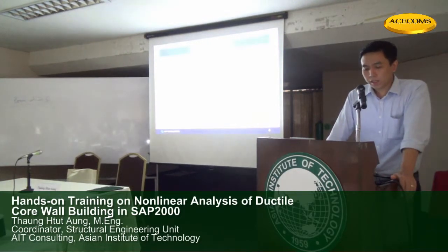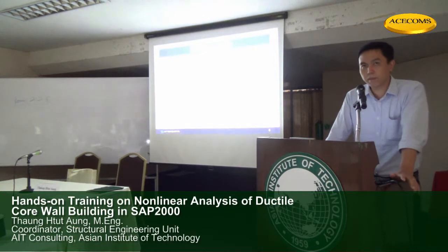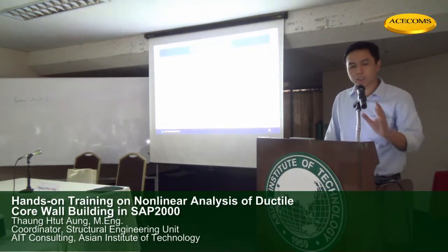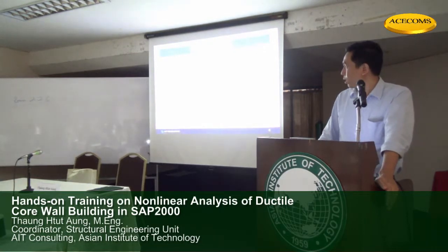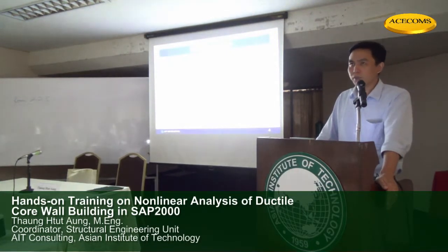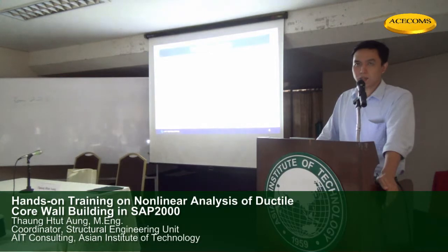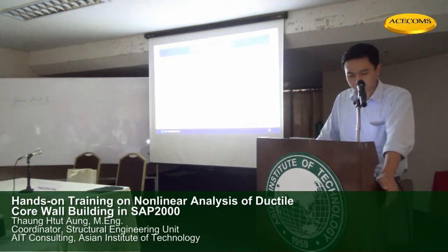We have to check the mode shapes, natural periods, modal participating mass ratios, base shear, base moment, shear wall frame interaction, story drift, story displacement. These overall responses we have to check carefully. If the overall response, like mode shapes, the first modes are not pure translation, the torsion is dominant in first mode, so we have to revise and modify the system in coordination with the architects.